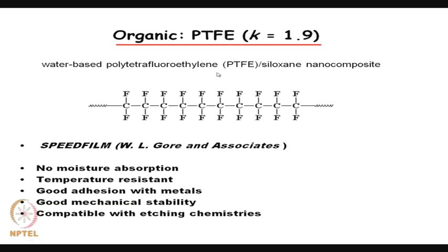So, now with this discussion we can conclude, so far as the low K materials are concerned, it is very important that this material is used in the interconnection, and this interconnection network must have a low RC value. With this low RC value we do not change R, generally copper is used having very low R, but C we can have different types of materials as discussed earlier.